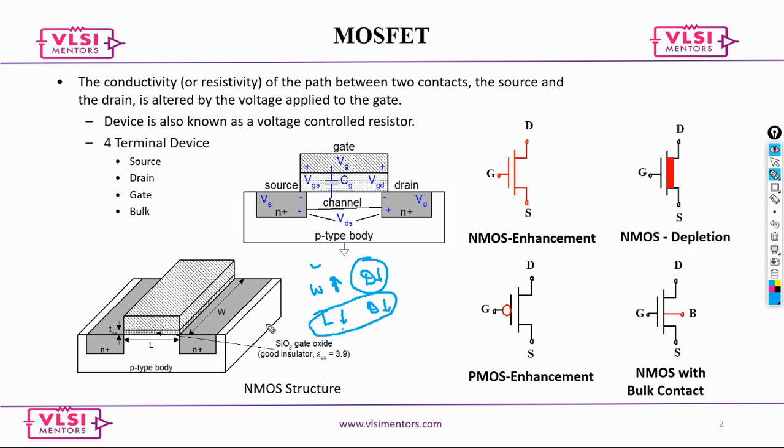Now, with a higher W, you will be able to charge this particular node, say this drain, either up to the VDD level or the VSS level quickly, because you have a bigger W. Now this would actually bring down your overall delay.